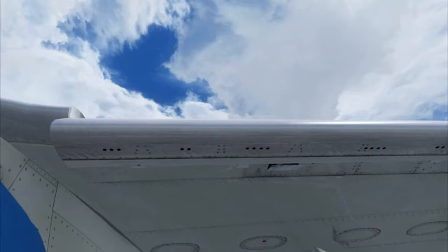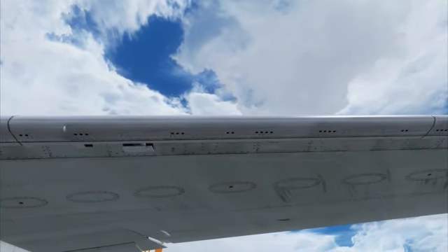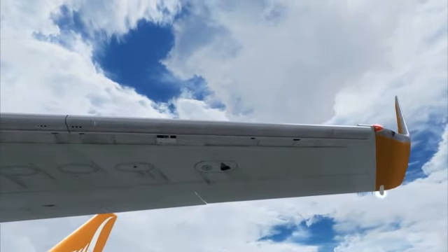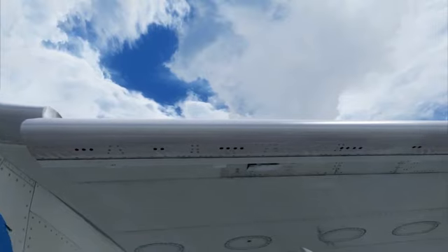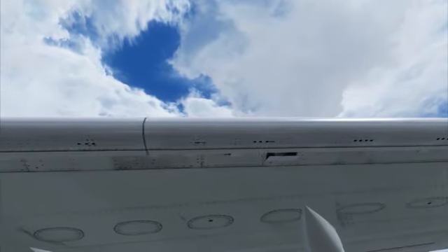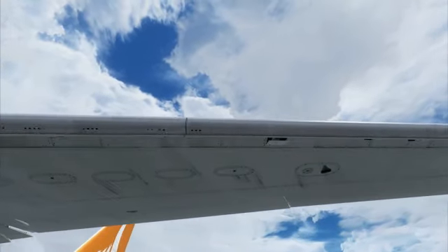The wing anti-ice system also uses bleed air from the pneumatic system. Bleed air is ducted through the 3 inboard leading edge slats on each wing to provide ice protection. The leading edge flaps inboard of the engines are not protected, and neither are the outboard leading edge slat panels. These were deemed too thin for the required ducting, and tests conducted with artificial ice shapes did not degrade aircraft handling or performance significantly. The bleed air is exhausted overboard once it has passed through the ducting, and the exhaust ports are clearly visible on the leading edge of the wing. Note how there are no exhaust ports on the outboard slats.